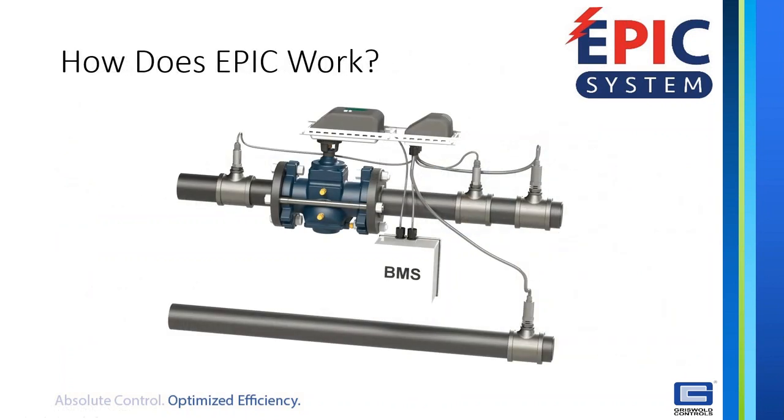So how does EPIC work? Well, the EPIC system measures the energy usage while monitoring the coil performance, really. So it adjusts the pressure independent control valve to optimize your coil's performance. Each coil has an optimum delta T, that's the temperature drop. The coil manufacturers, boiler, everyone that does some kind of heating or cooling has an ideal delta T. And so the EPIC system adjusts the pressure independent valve to optimize that coil performance.